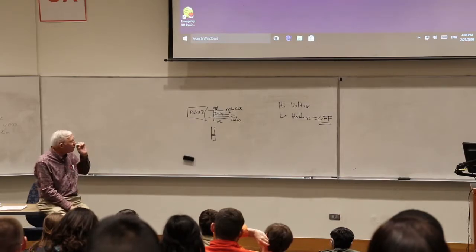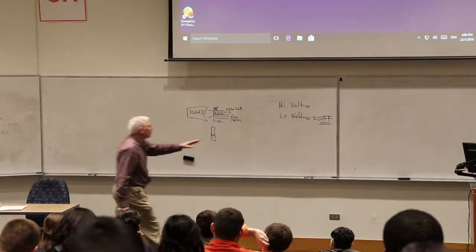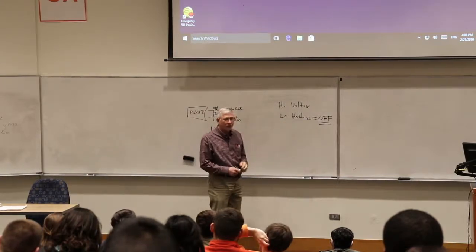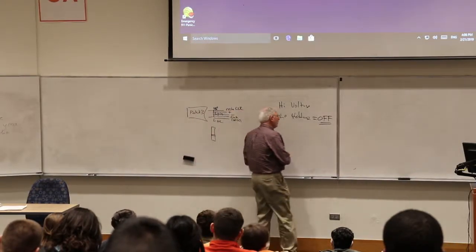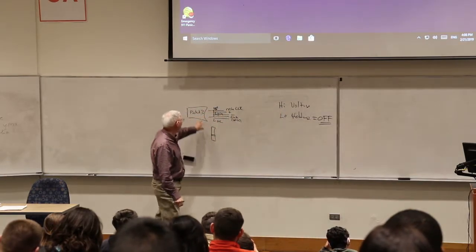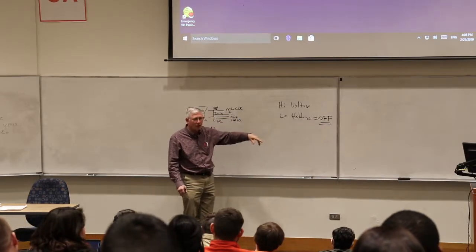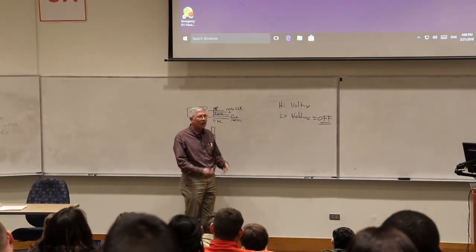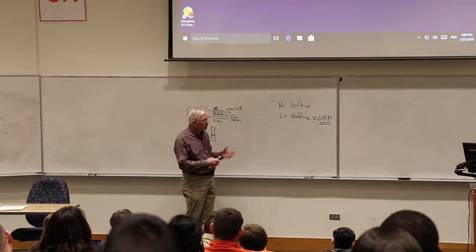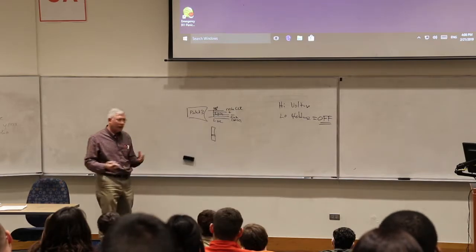But if you have programmed your chip with a PICkit 3 with the low voltage programming turned off and not on, then you can't program it with the Snap. You have to go back and program it again with the PICkit 3 and set the configuration bit for low voltage programming to on. And then you can program it with the Snap. I didn't know that, and that was news to me, but that's how it works.